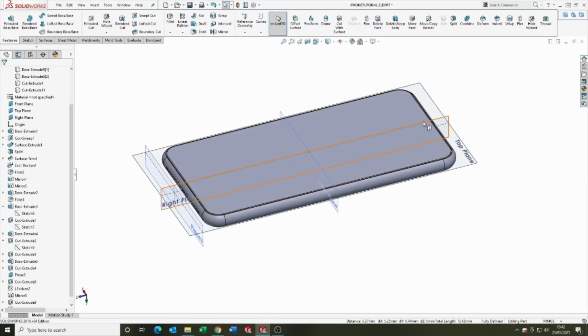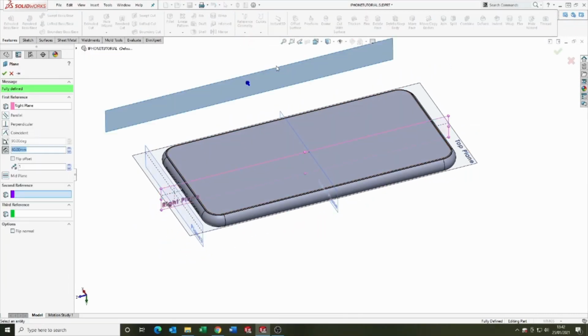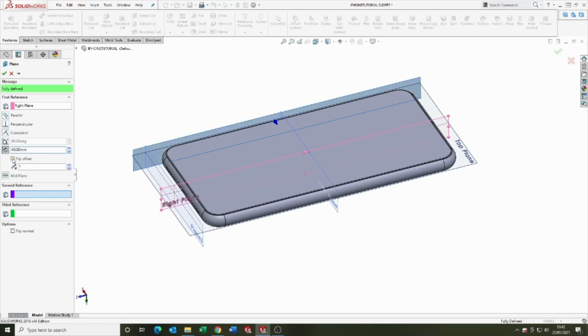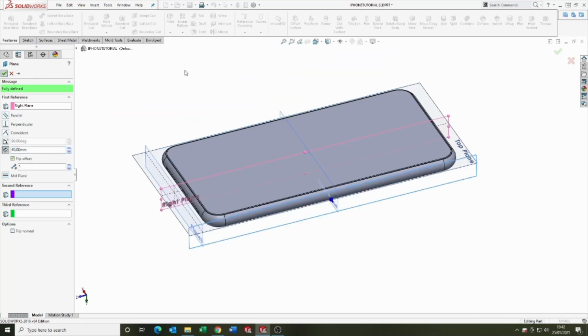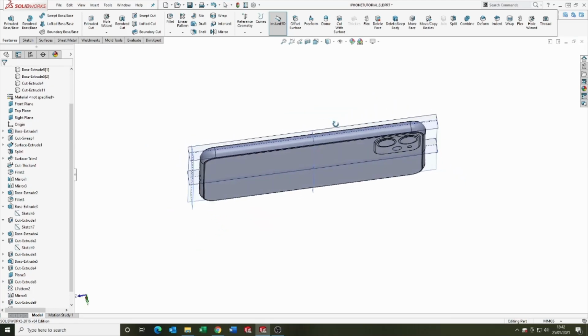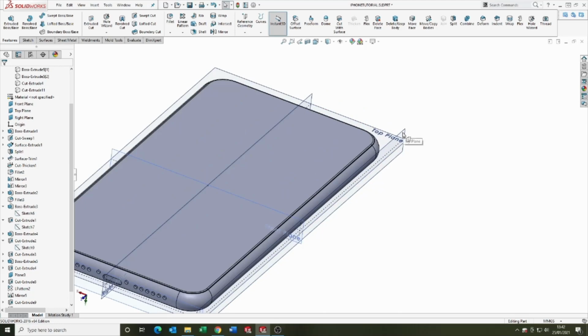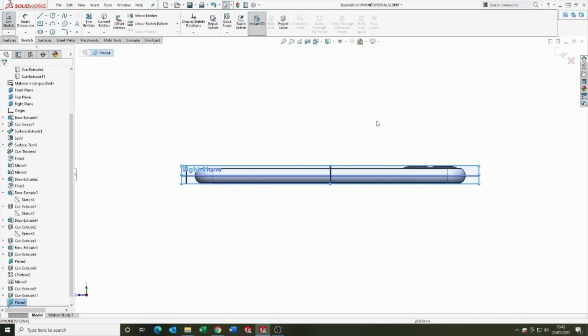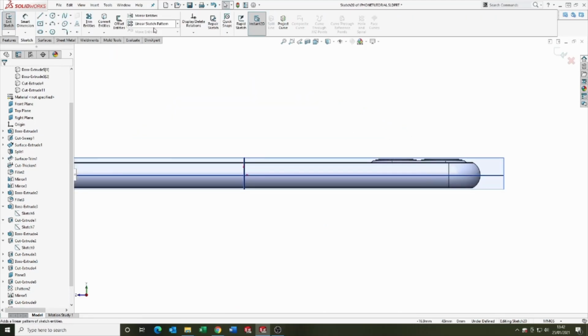So this is the final talking I'm going to do over the video now. Just going to create a reference plane on the side. So 80 divided by 2 is 40mm, flip the offset. And this is the process for creating the buttons in a multi-body part. The process is repeated for all of the buttons, so I'm just going to talk over how we did it for one.